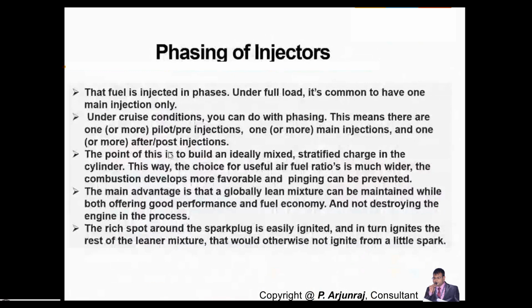The phasing will also vary with respect to different conditions. For example, when the engine is running in full load condition, here they consider only the main injection, whereas when the engine is running in cruising condition, they mention going for one or more pilot, pre or post injections.